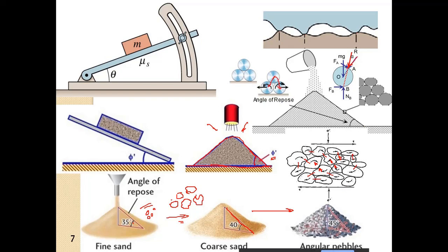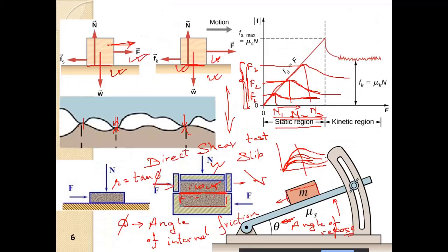So there are forces onto the soil, and that is how this mound is kept stable. These are the interparticle normal forces, and there will be shear forces just like this. This angle of repose is also comparatively equal to the angle of internal friction, so you can correlate this to this. Here there is one solid particle, and we have the points of contact, just like in the previous case.